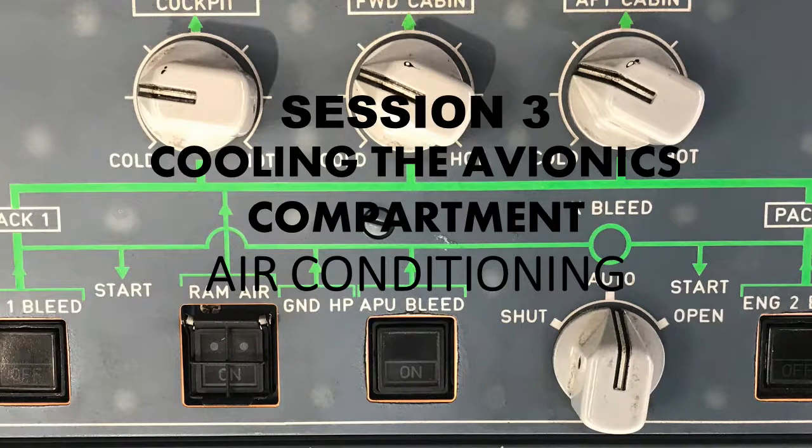All right. So that's your skin air inlet and outlet valve. Just so you know what their conditions or positions are: when the aircraft is on the ground, it's fully open. When it's in flight, it's fully closed.